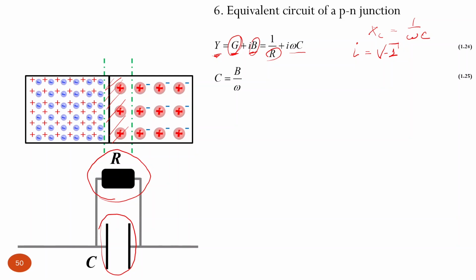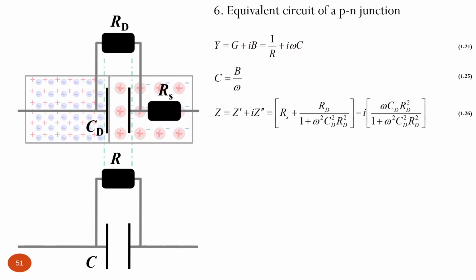So now if we get this susceptance, we can easily determine capacitance. We just need to divide susceptance by the frequency of the AC signal at which we measure this susceptance. Obviously, it will be a frequency dependent parameter. Everything easy peasy, but the problem is that in real life we need to consider a little bit more complicated